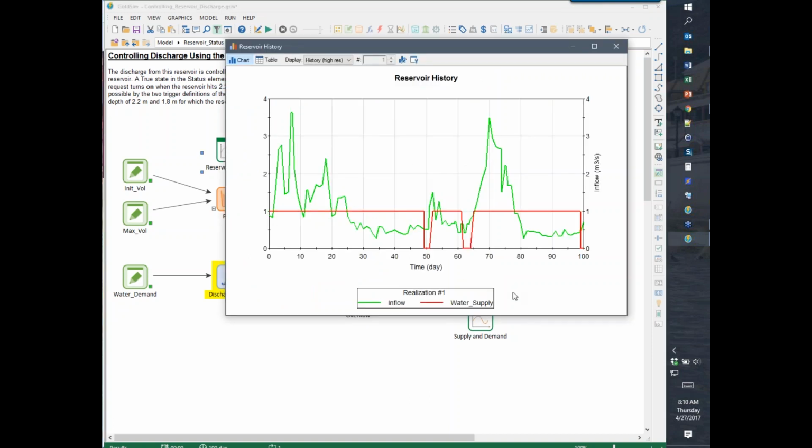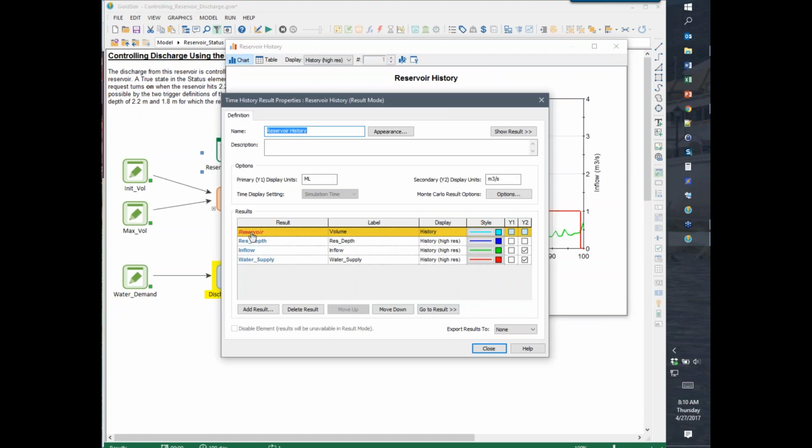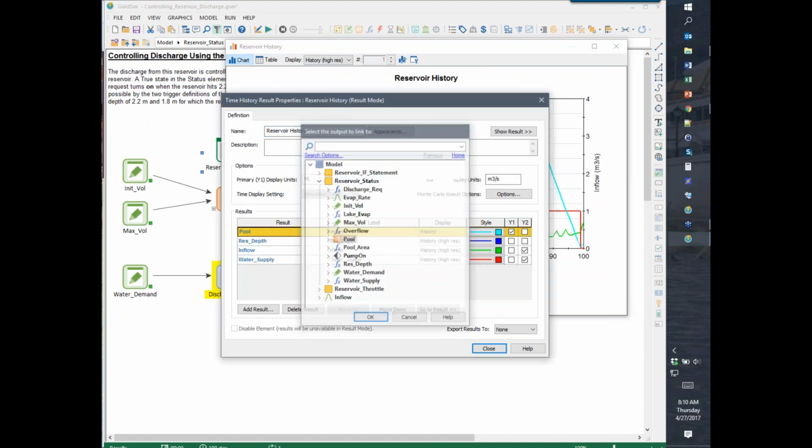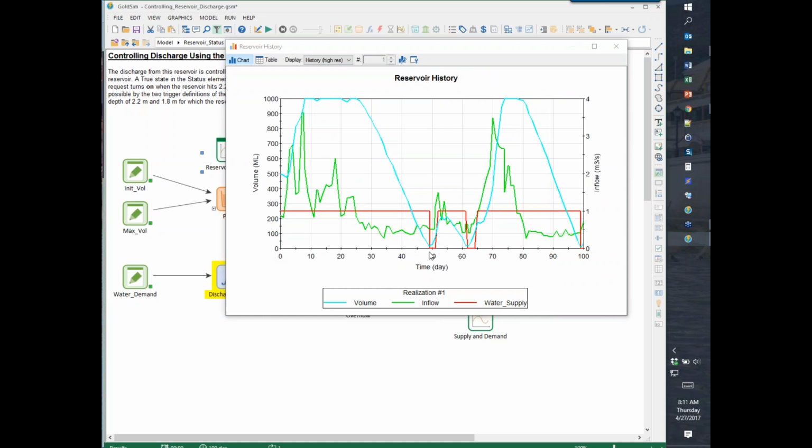And so here you see the reservoir, and I need to add the reservoir. Looks like it got turned off somehow. Okay, so when the reservoir level draws down to some point, we shut the pumps off and we keep them there. Even though the reservoir is rising, we just keep them there until we say, okay, the reservoir has come up enough, now let's turn it back on. So it prevents some of those oscillations.